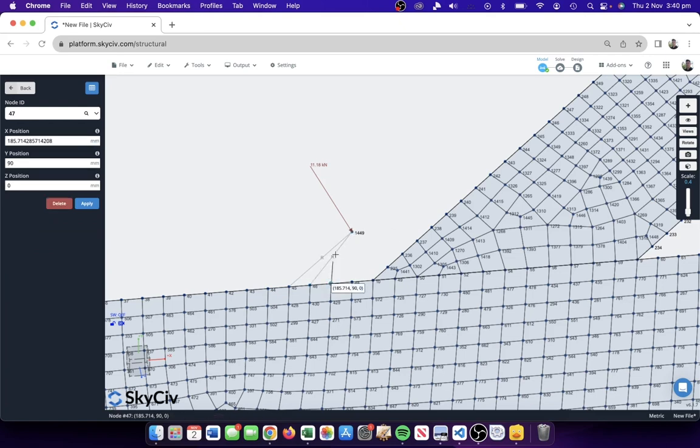So we're going to actually change the distribution of this member to connect to all of these nodes and distribute the force among all these nodes rather than just applying it to a concentrated point. And I could have chosen any distance. This node, I went up 20 millimeters. It doesn't matter, because I'm connecting it by rigid elements, so they'll automatically transfer all of the load, bending moment, shear force, everything from this node to these nodes, so evenly distribute the force there.